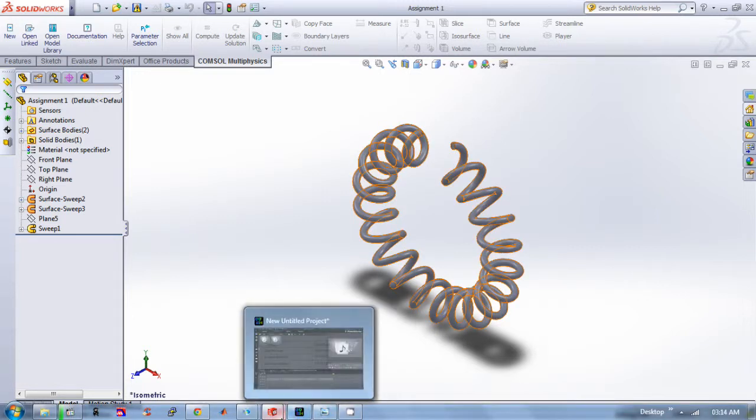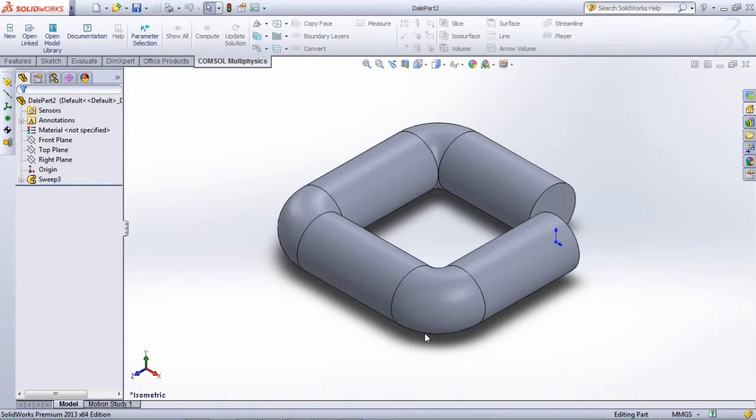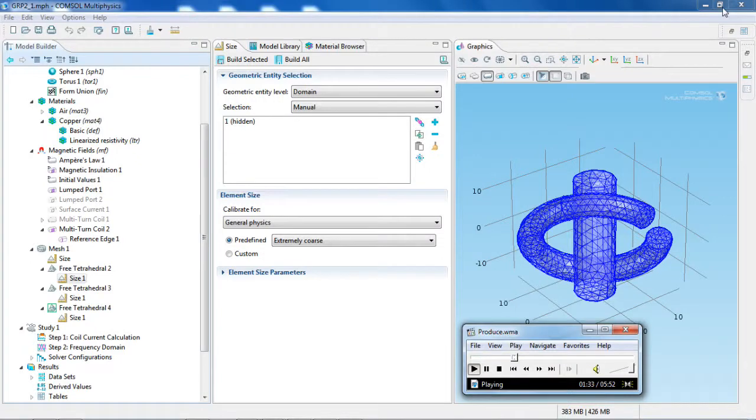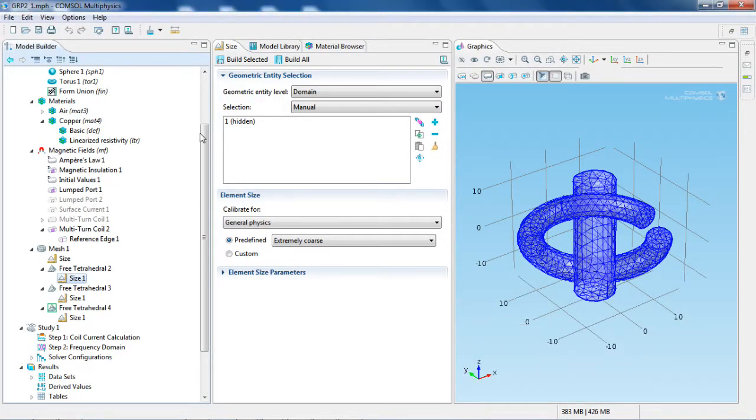The characteristic non-ferromagnetic core of the Rogowski coil results in its low inductance. As a result, the Rogowski coil's current response is linear, immune to saturation, and fast responding.